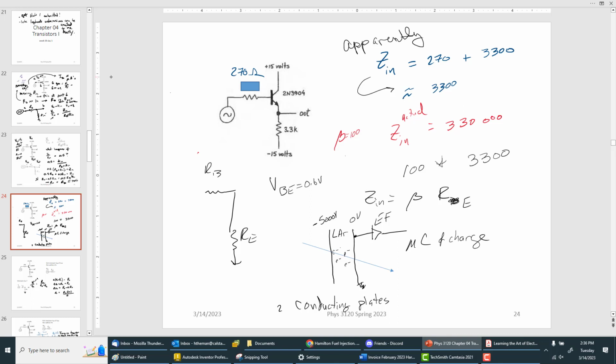And because of the high voltage, they march across to the right. And in principle, they can induce a tiny signal. Typically, in one of these things, the time that it takes for them to drift across is 400 nanoseconds. And you figure out that the current is very low. And if you have a very high impedance input, you can get a nice voltage.